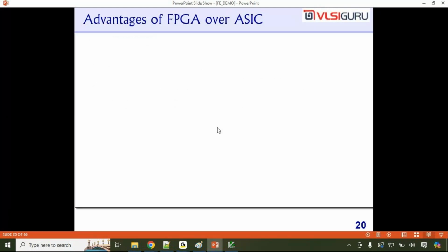It's because of the way it's manufactured on the board, and because of the way the FPGA cells are arranged, because you don't have much flexibility with the connections of all those things, right? They're already pre-implemented, so you don't have much flexibility to control, I mean, to do any timing closure at higher frequencies. Whereas in ASIC, since you are doing everything, you can adjust it in such a way that at higher frequencies also we can do the timing closure.